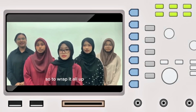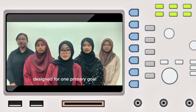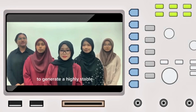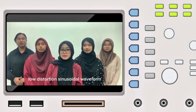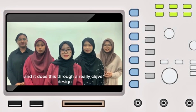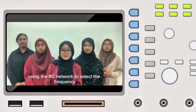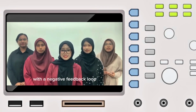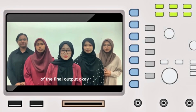So, to wrap it all up, the Wien bridge oscillator is a fundamental circuit designed for one primary goal: to generate a highly stable, low distortion, sinusoidal waveform. And it does this through a really clever design. It perfectly balances a positive feedback loop using the RC network to select the frequency, with a negative feedback loop that controls and stabilizes the amplitude of the final output.